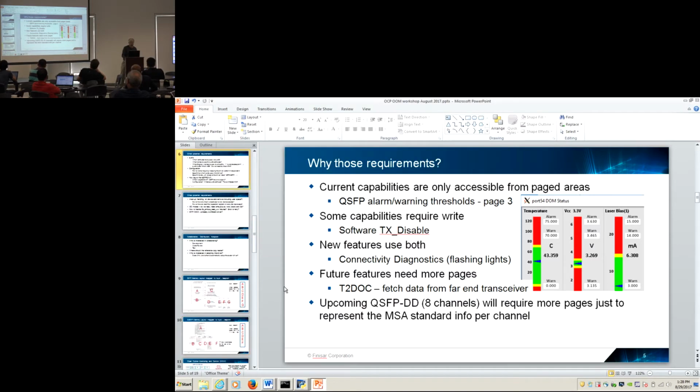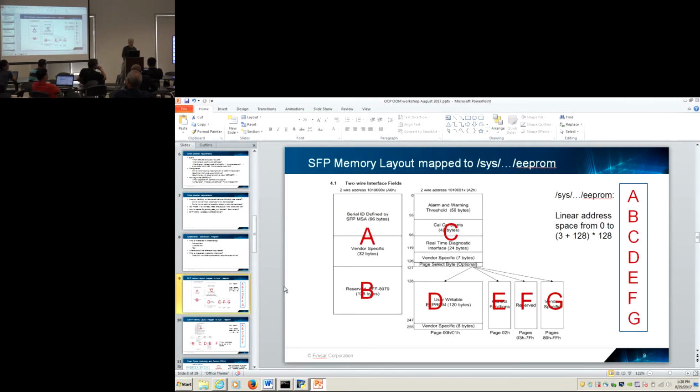All right, so now I want to go to, is C Cisco? No, CFP is Compact. You want to explain? Well, it's where the 100 gig interfaces started, and we couldn't put them in the size of a QSFP. So it's designed for a larger, more complicated format. It has a completely different layout in the EEPROM. It's accessed by MDIO, not I2C, so we're going to need a new driver, but OOM just says, where's it at? How do I decode it? Let me provide it for you. So the same simple interface can basically go through all the plumbing and get the data for you.